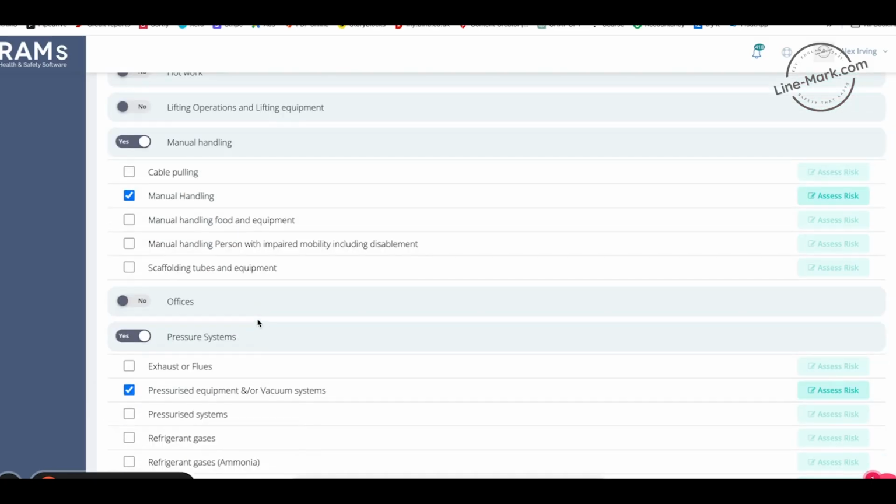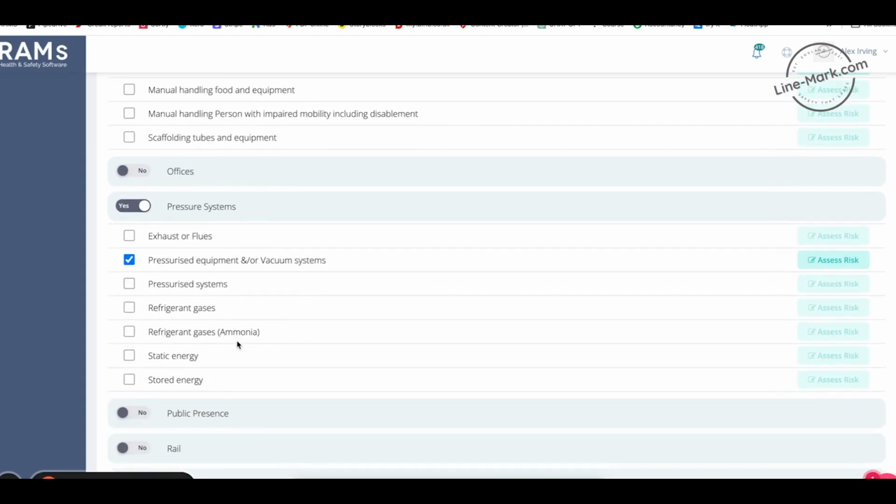And as you know, I don't like spraying any lines indoors, I prefer to hand roll, but for this one we may be spraying on some walking men, so we'll just put down that we're going to use spray as well. And then lastly, bit of manual handling again for lifting the equipment in and out. It's a pressurized system. When we're spraying the walking man, for example, we're going to build up 1500 to 2000 PSI on the machine. So we do have a pressurized system to take care of as well.